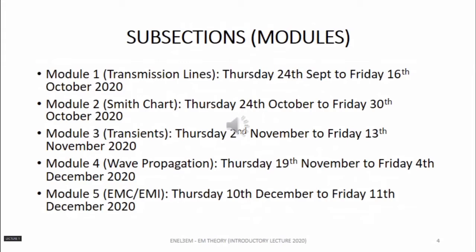Then we'll focus on different types of transmission line. We have a typical lossless line, which is an ideal line. Then we have a distortionless line. We have a low loss line. And for each of these, we'll determine the corresponding parameters. That is the characteristic impedance, and we'll also determine the propagation constant, out of which we'll be getting both the phase constant and the attenuation constant.